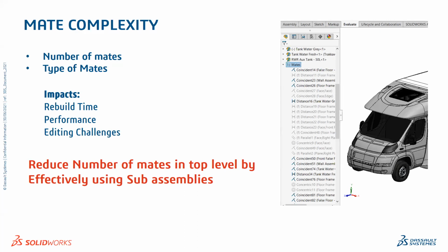The number of mates will definitely impact our rebuild time, performance and editing challenges. So when you have larger components, you will have larger mates at top level. One mate will be depending on multiple components or multiple mates also. That is where our editing challenges will come.